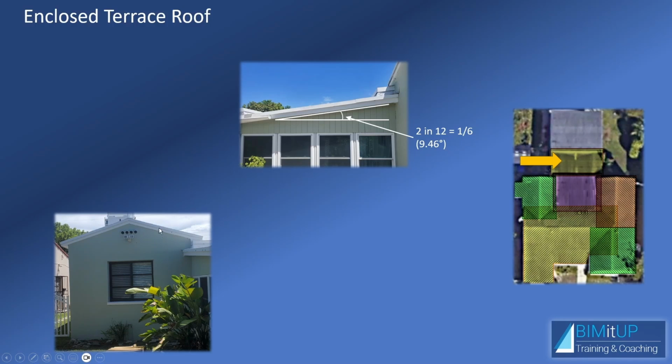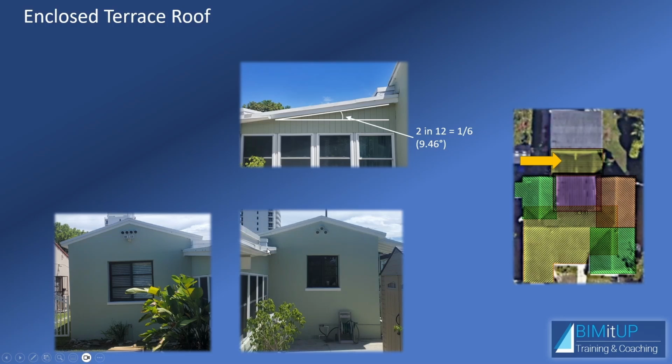And here you can see the east side, which is the north bedroom, and you see how it interacts. And then this is the other side towards the kitchen. The roof characteristics are: to the east and west, we have an overhang of 10 inches, which is this one. To the north, we have a small overhang of 8 inches. And to the south, it's not applicable because, as you can see, it meets with the kitchen wall and it meets with the bedroom wall.